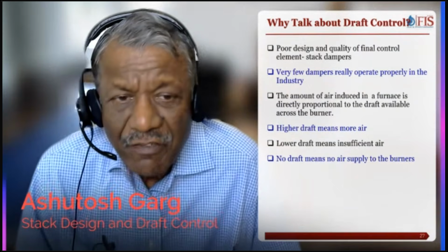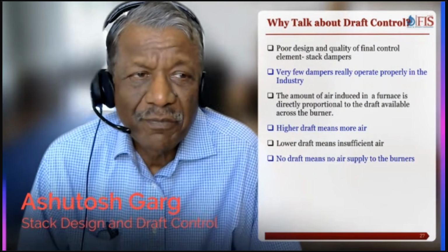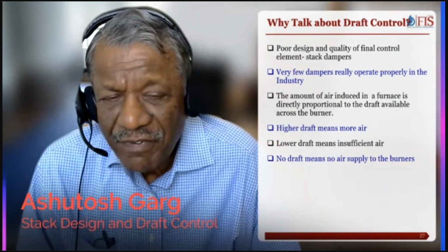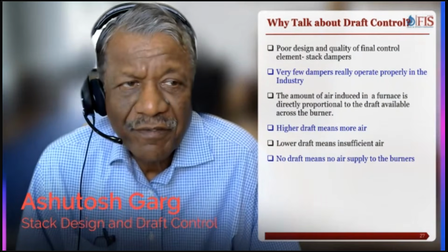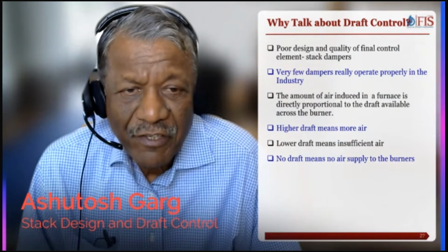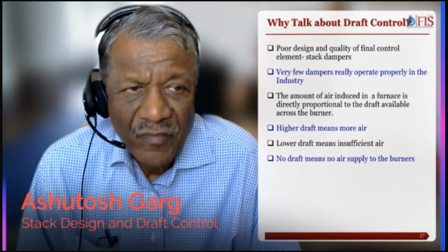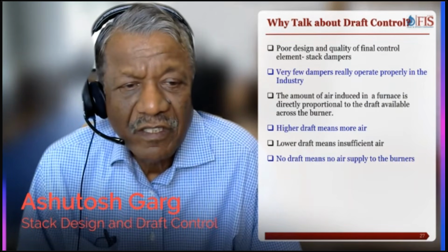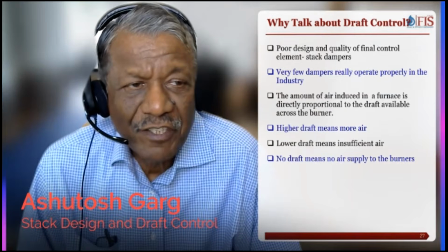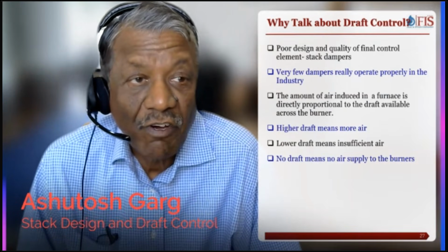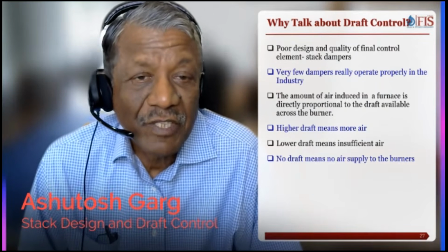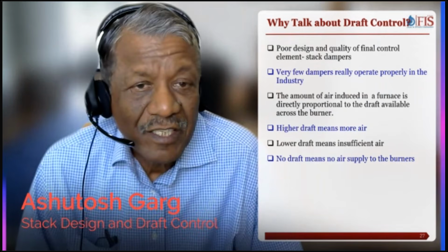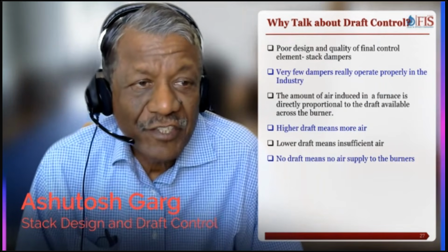I would say part of the time it's the fired heater industry which is to be blamed. Most of the fired heater industry treats the stack damper as a plate on a rod, and nobody thinks of the stack damper as a control valve. Whereas it is a control valve. It is a final control element. If you ask any instrument engineer, that is what it is, but it is not given that treatment.